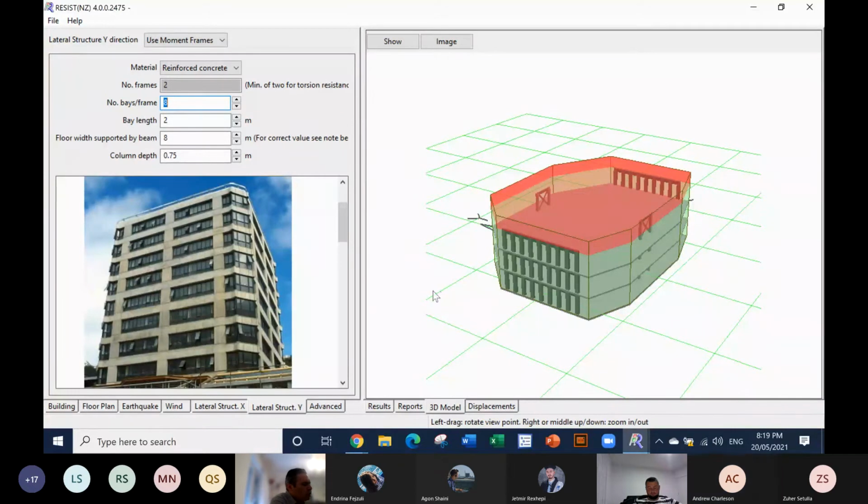But I think eventually, continuously increasing the building height, you have to turn to steel. You have to put structural steel, because of also the compressive capacity. So you have concrete like 40, 50 megapascals. On the other hand, you have 500 megapascals steel. And if you mix them together, that's when you push the boundaries. I am sharing my view now, because moving like 400, 500 meters and above, you have to introduce a new, stronger material.